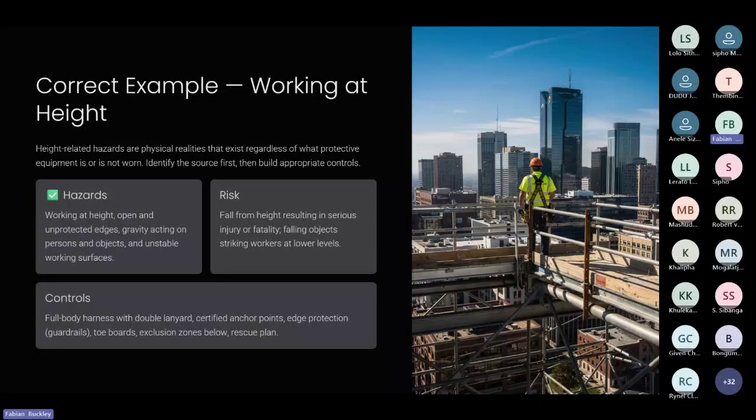If we prevented people from completely coming into that area at all, meaning it was fenced off, there were security guards below, etc., we could have taken that even as we've eliminated the potential hazard of something falling onto an employee below. So we can take that right up to a possible elimination of anybody entering that area from a hierarchy of control perspective. And then the rescue plan and the rest of them, your toolbox talks, your DSCIs, your permits, that's all obviously part of our administrative controls, which includes our signages as well.